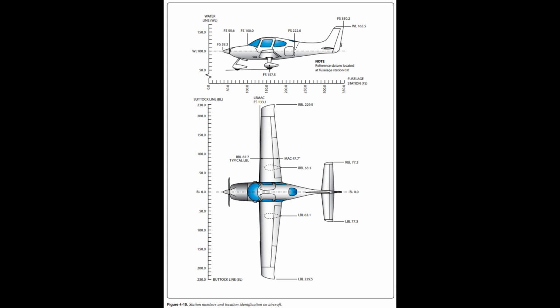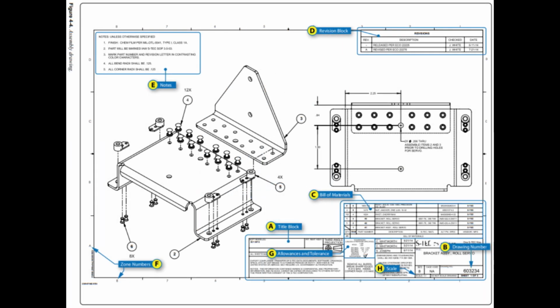Allowances and tolerances. When a given dimension on a print shows an allowable variation, the plus figure indicates the maximum, and the minus figure the minimum allowable variation. The sum of the plus and minus allowance figures is called tolerance.